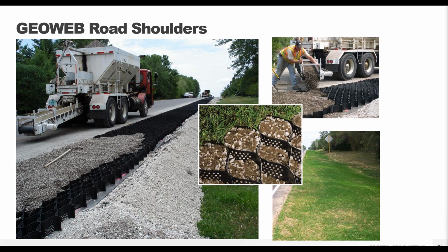So you can use this to widen your roads, and it can help manage stormwater runoff from your asphalt or concrete roadway by collecting that water and allowing it to infiltrate without running off and potentially gathering in a side area or needing big drainage swales to collect and move that water. You can just infiltrate it naturally into your groundwater system.